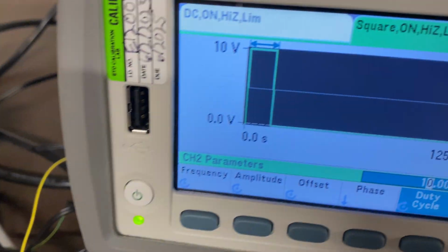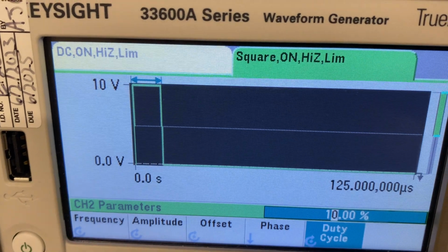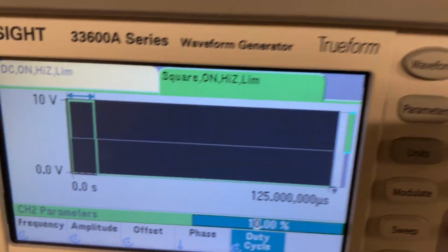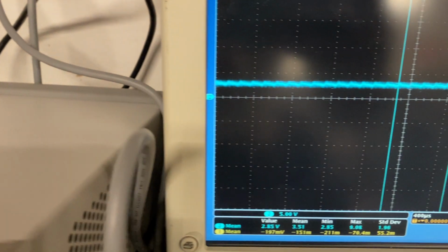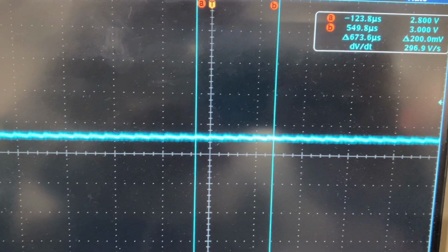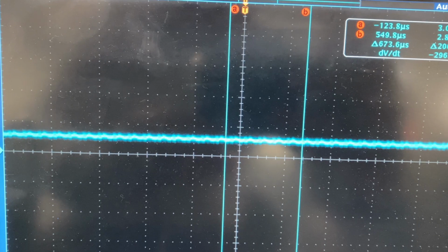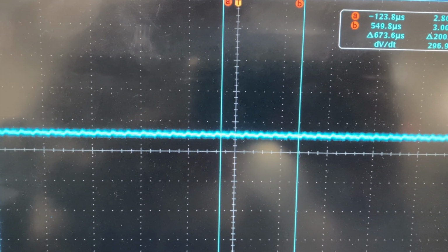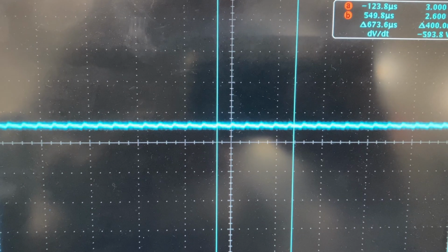The peak voltage of the PWM generator is 10 volts, and it is sufficient to drive this N-channel MOSFET for this simple demo. In a real application, we would use gate drivers to switch the MOSFETs, typically supplying up to 15 volts to turn them on, but that is a discussion for another video. I've used a switching frequency of 8 kHz for this demonstration.